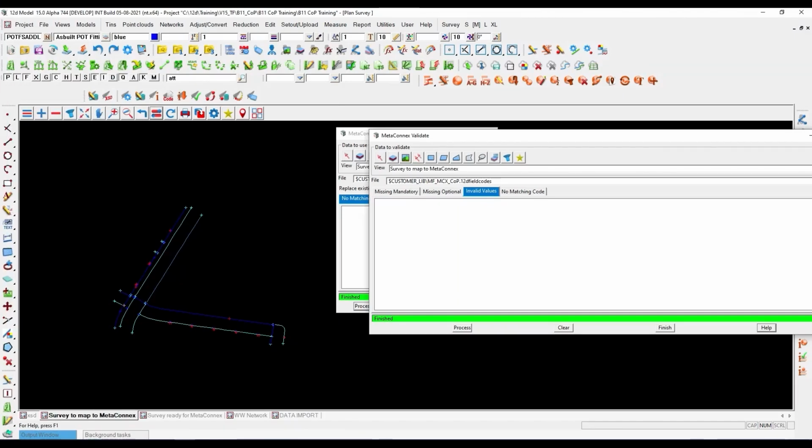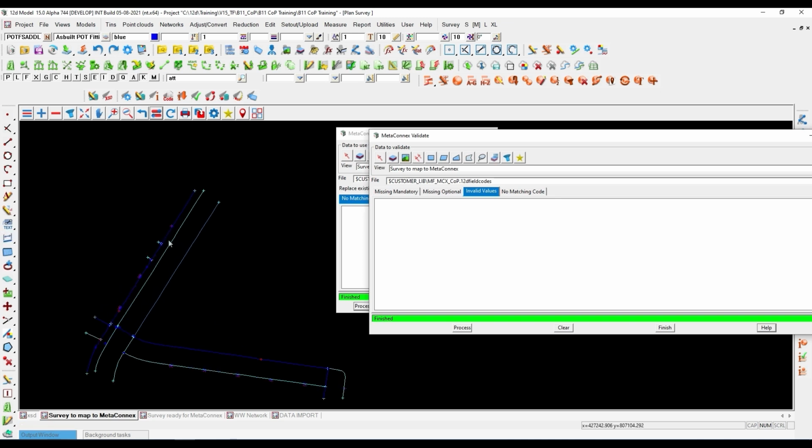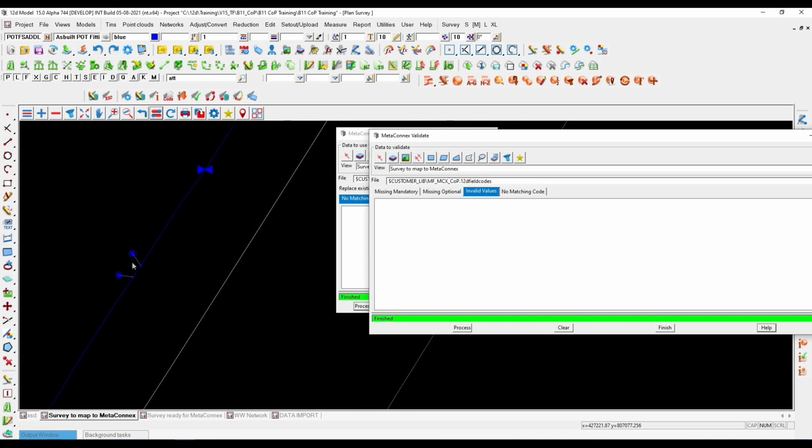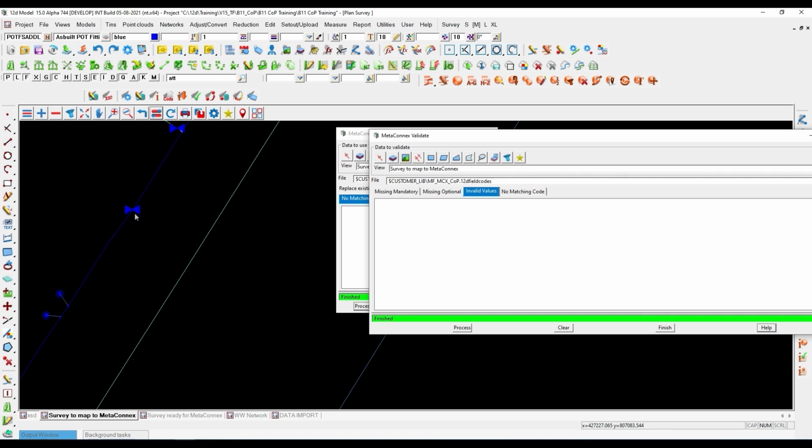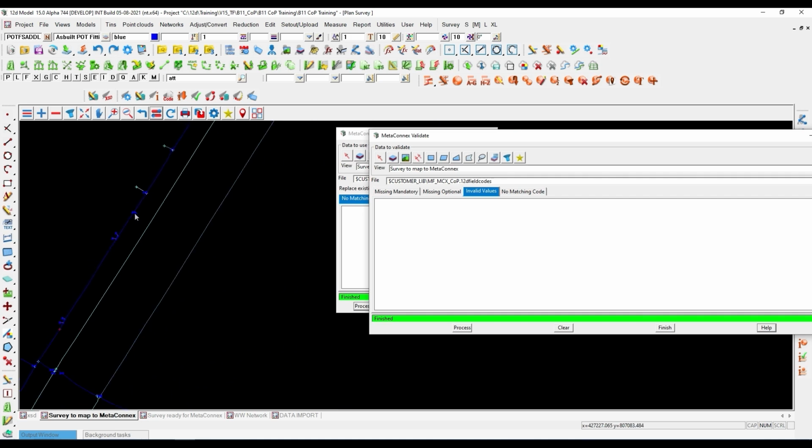Within the code of practice for the potable water, there's quite a few things that need to be required. The code of practice requires that an asset, a pipe asset, I should say, should have a start point and an end point. In this case, it would be a water tapping band, and the end point will be a water toby or water meter. Down here in Otago, we actually have one box that has both assets in there, so two different types of assets. And we need to have unique identifiers on each of our hydrants and our valves, and a unique identifier on our pipes.